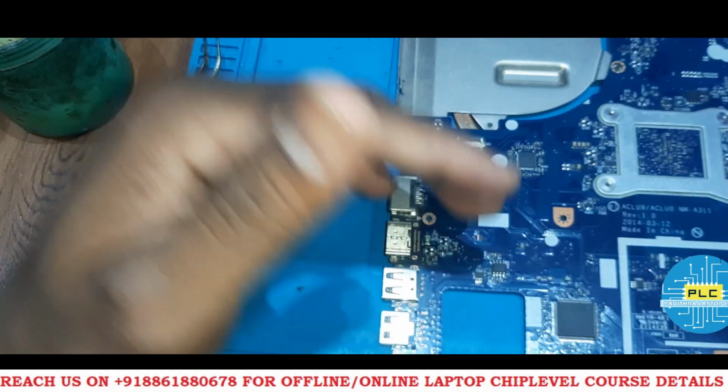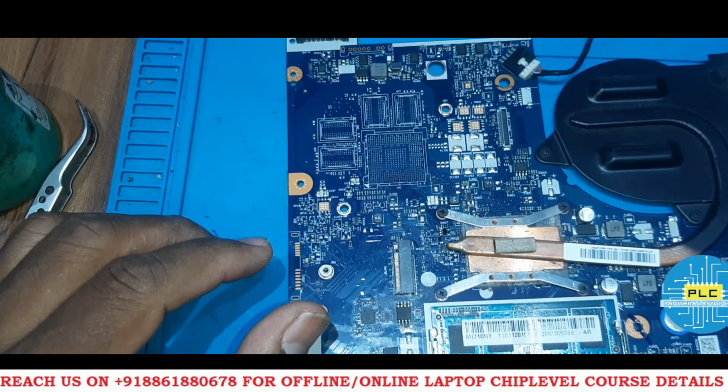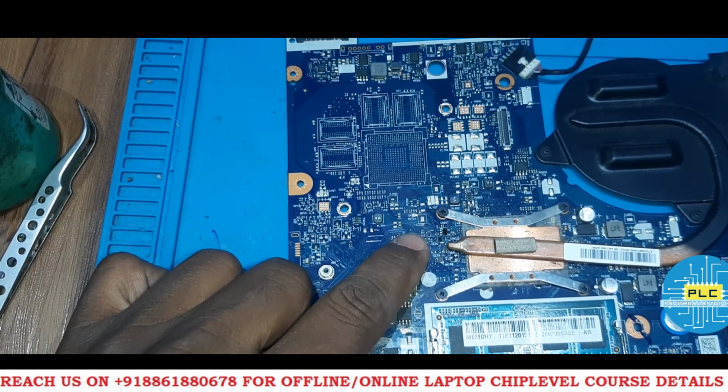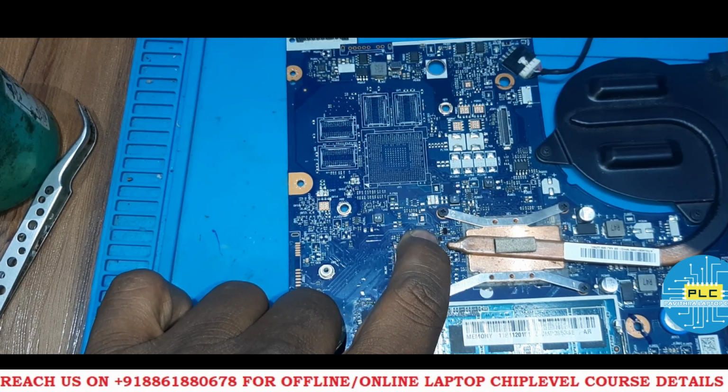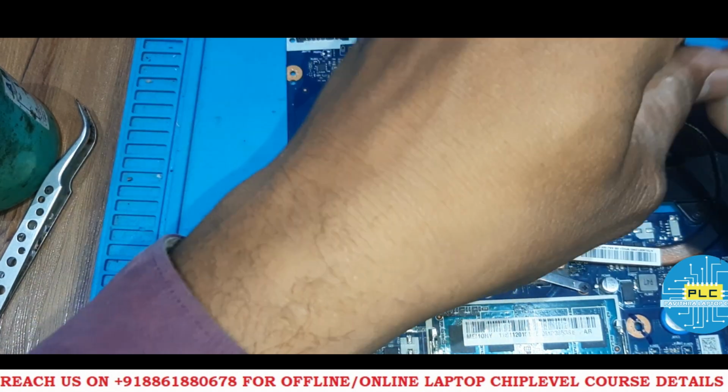Okay, now I'm going to remove some other jumper section, so let us check. See guys, here I have removed PJ702. What voltage is it? It's 1.0 volts always, VALW voltage. So now we will check, we are going to connect it now.